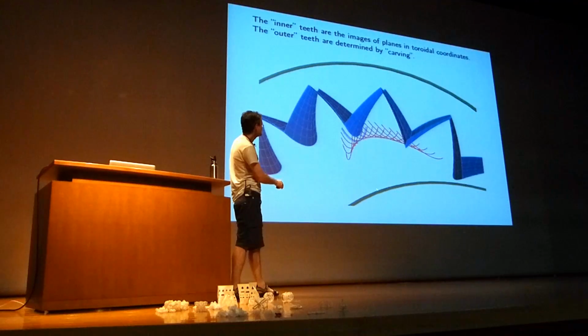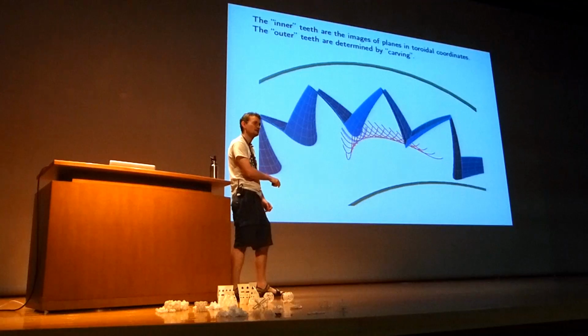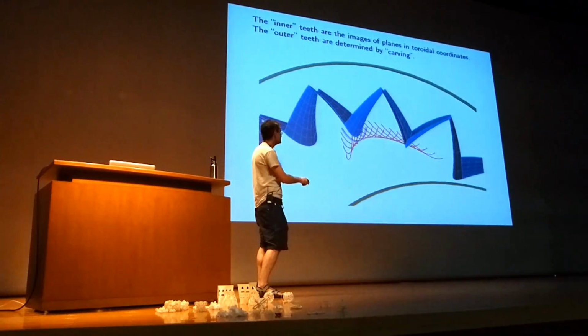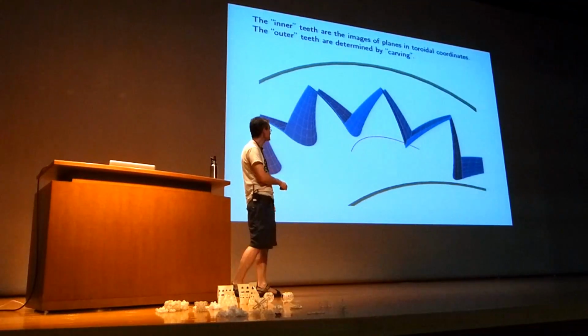So what's going on here? Whatever the shape of our gear tooth on this ring down here is, it can't have any pieces up here, because if it did, then it would crash into the blue gear teeth as they rotate. However, I can have parts of the gear that are underneath all of these things. So if I have a shape of a gear down here, then it will closely track this edge of the gear up here. And so that's what we do.